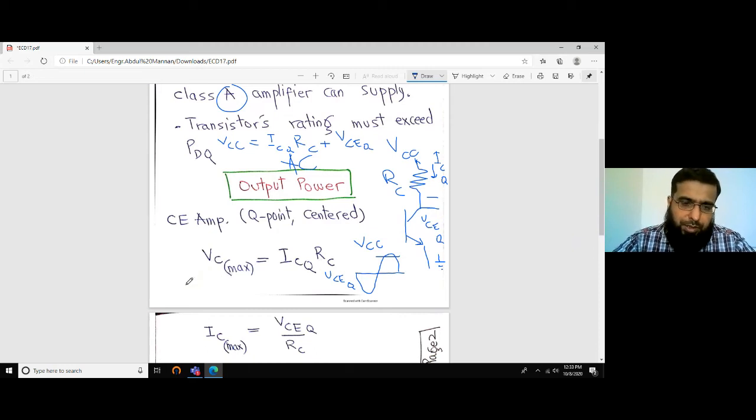This is actually the peak value of the AC signal. We have studied in our earlier courses, like in LCA, linear circuit analysis, that the peak voltage VP of a sinusoidal voltage is the maximum voltage attained on the positive side or the minimum voltage achieved on the negative side. So it gives us a peak either on the positive or on the negative side, which are the same in magnitude.